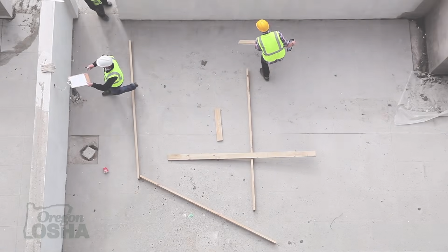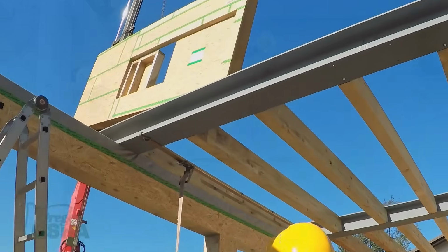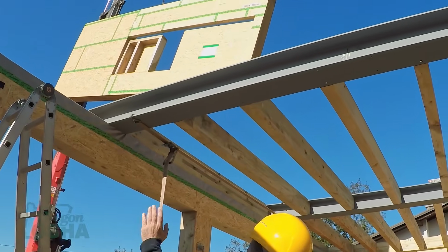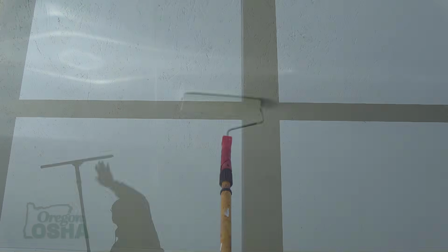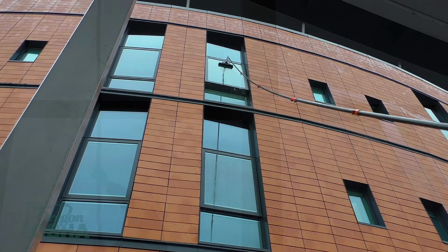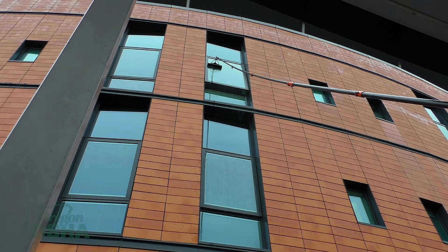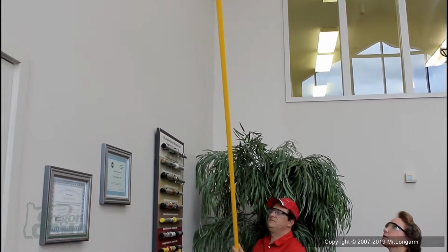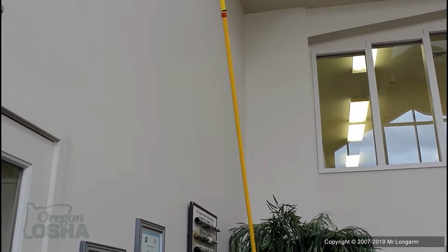Here's some examples. Perform construction work on the ground before lifting or tilting components to an elevated position. Use tool extensions whenever possible to allow work to be done from the ground. Sometimes, substituting one piece of equipment for another one that doesn't put workers at risk could eliminate the fall hazard. This may require some extra planning before a job, but could really pay off in the end.